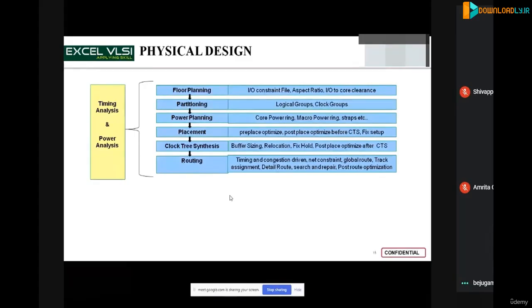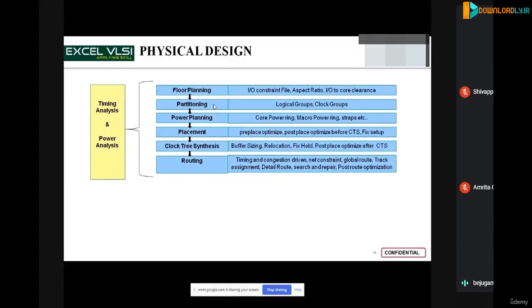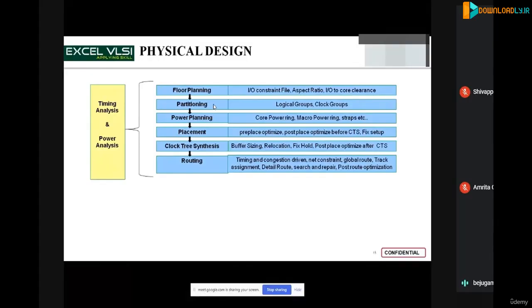So that is partition, I mean to say that group of logic is separated at this particular stage. Once the area estimation of the complete logic is defined, it is divided or split according to the functionality logic it has converted into gates. Now obviously once the circuitry has to be in the process of running, we need some power. So to turn on the circuit, we do some power planning with the circuitry we have, and that stage is nothing but the power planning stage.